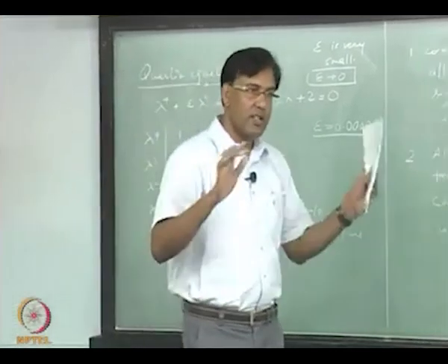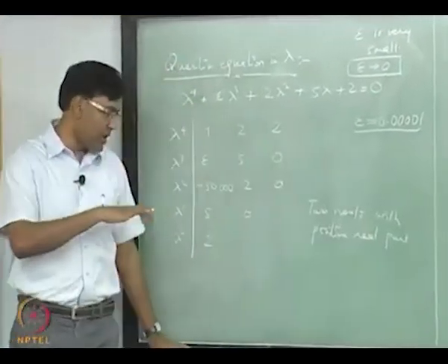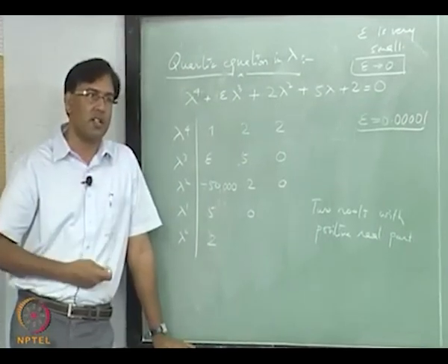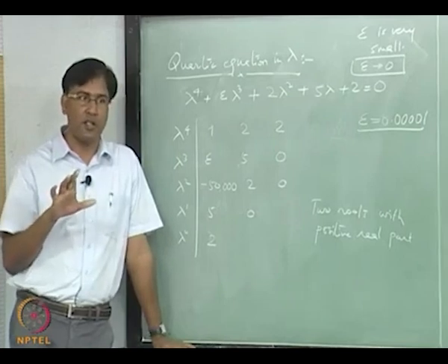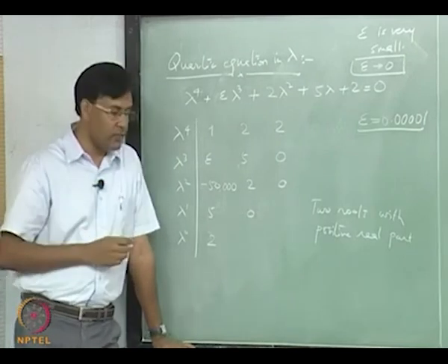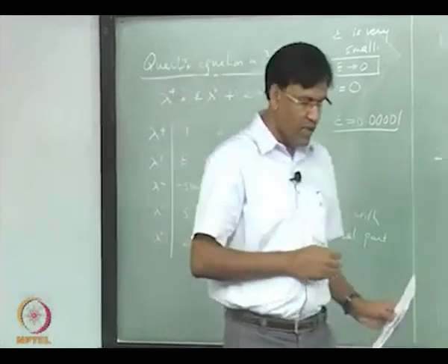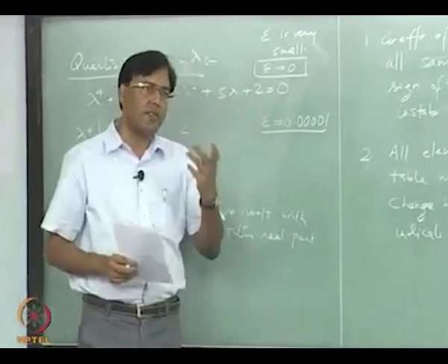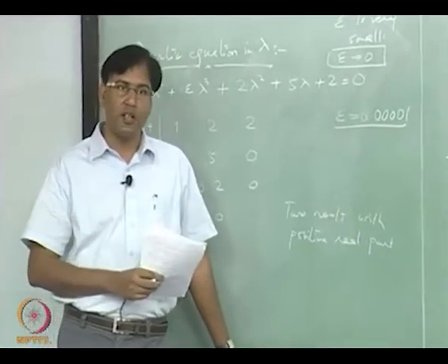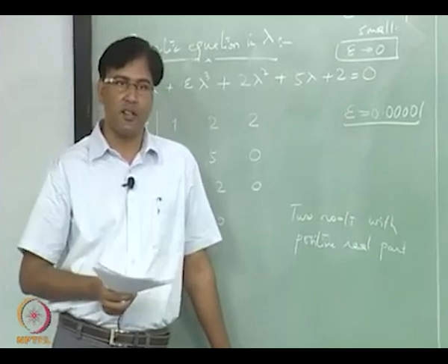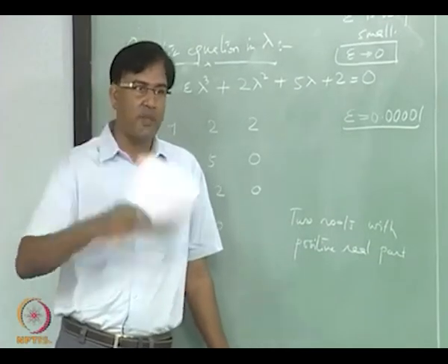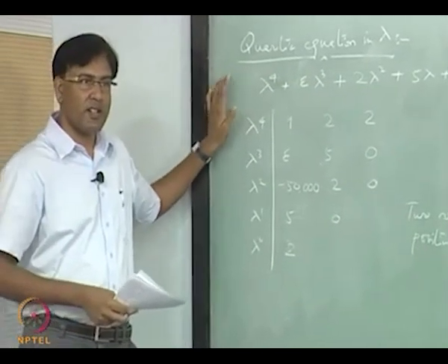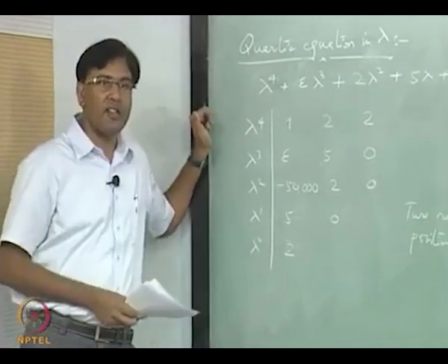Okay. So, it's actually complicated. You think about the 8 equations that you have to talk about when you talk about coupled motion. Rolling is a coupled motion, roll maneuver. So, what you have to do to study the stability of the aircraft in that maneuver, you have to look at all 8 equations, right, and 8 equations linearized means you get an equation which will have lambda to the power 8, right.